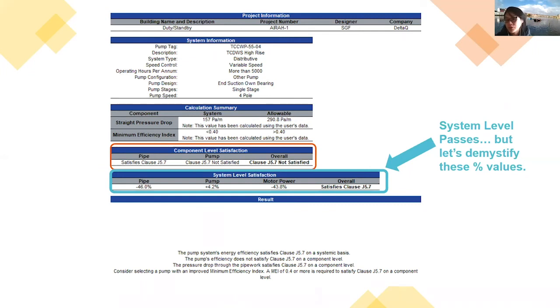And on the straight pipe work section, we have entered all of the detail into the spreadsheet rather than just taking our calculated average pressure drop per meter and entering it into the spreadsheet. The spreadsheet automatically calculates the whole of system compliance easily by you just clicking onto the report tab in the spreadsheet.